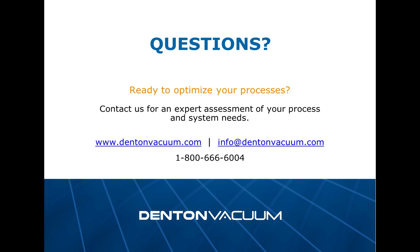Sure. Substrate temperature would always help with higher film quality. Typically, limitations on the temperature have more to do with the whole process integration, whether you have any thermal budget. For example, photoresist or your active layers cannot withstand the temperature, but high temperature typically leads to better film quality.